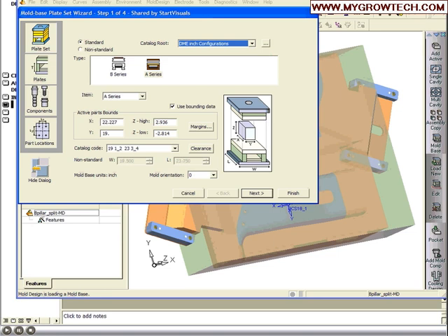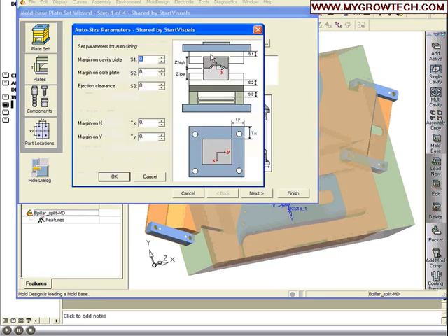Even if it's something really huge, or like a fascia or an instrument panel, model up the overall plate sizes, model up the guide bushings and the guide pins, and then save them. And the way that you see me going through this standard configuration, it will be exactly the same for your particular type of mold. So it's very flexible.